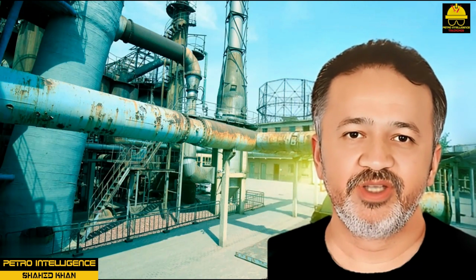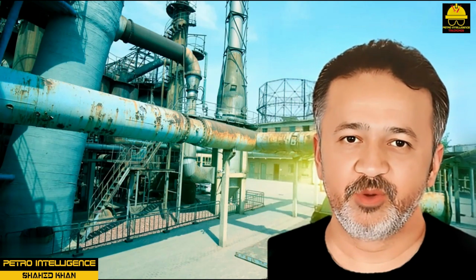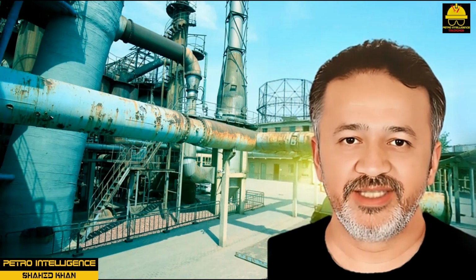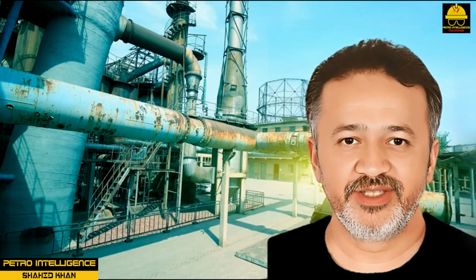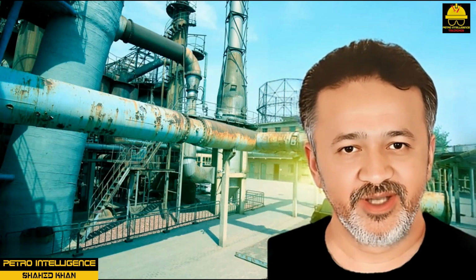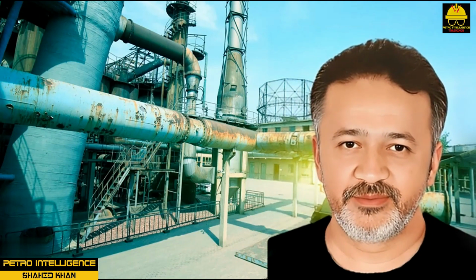Corrosion in equipment is typically associated with oxygen reacting with the metal, so a deaerator is used to remove air, which contains dissolved oxygen, from water. The deaerator heats the water with steam and dissolved oxygen passes out the vent with the steam. In demineralization, raw water is passed through anion and cation exchange resins.